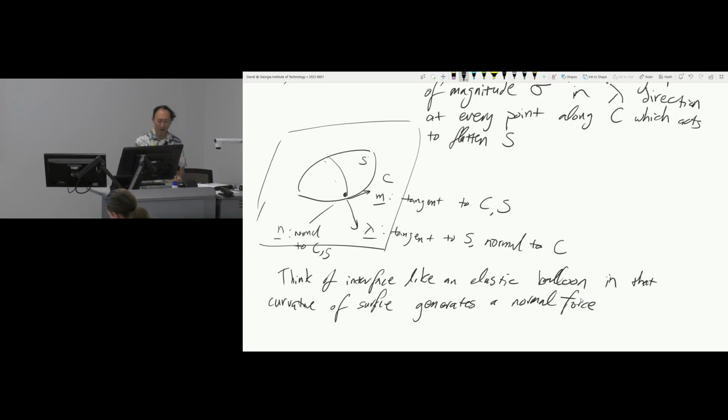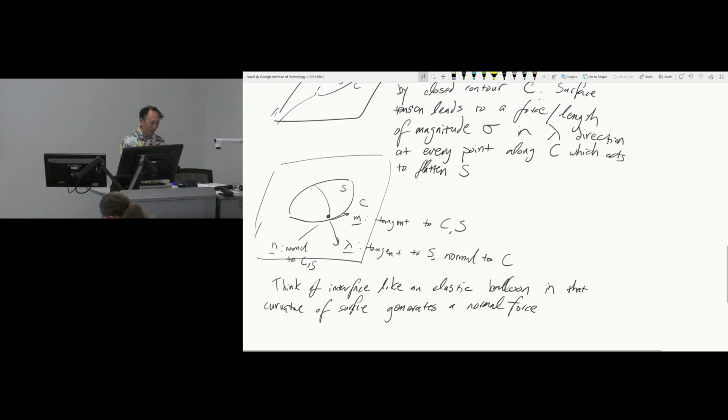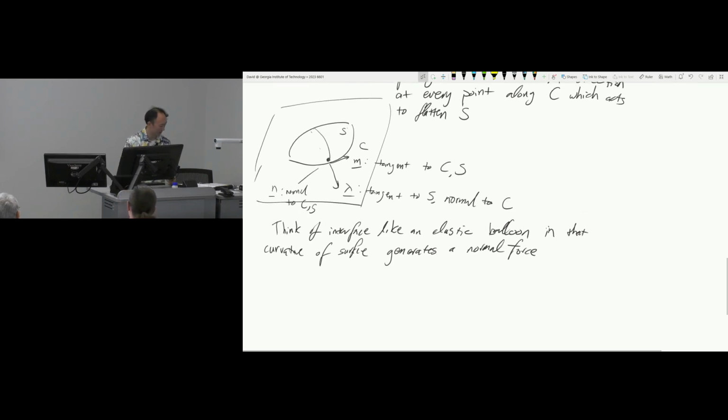All right, the reason we have to be careful about these vectors is that there are two types of force. There's something called Marangoni force, which is due to, as you saw, the Shimonagashi, those rings went outward. Marangoni forces are tangential to the surface, and there are normal forces that are perpendicular to the surface.